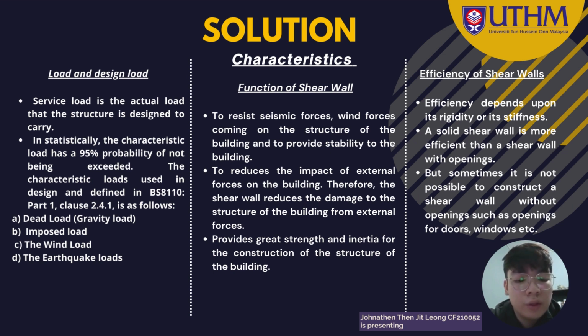The efficiency of a shear wall depends upon its rigidity, and a solid shear wall is more efficient than a shear wall with openings. But sometimes it's not possible to construct a shear wall without openings, such as doors and windows and so on.